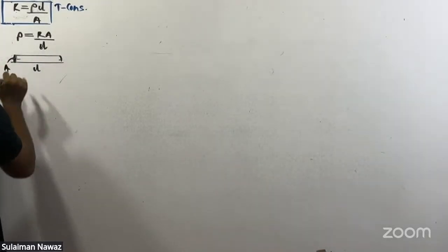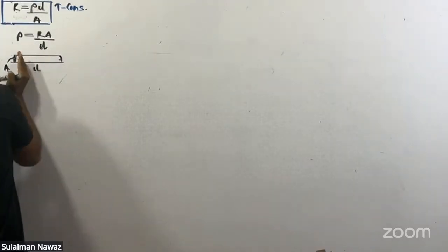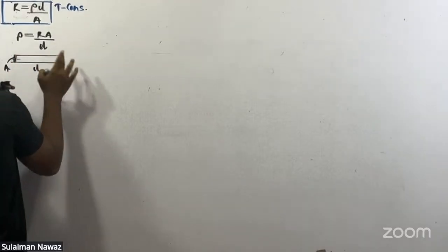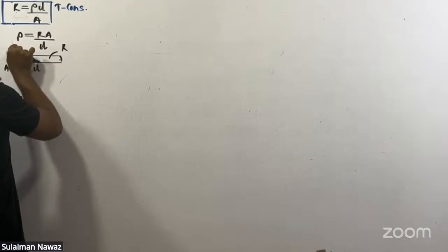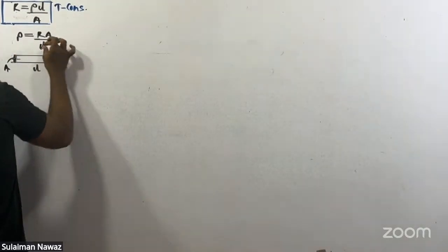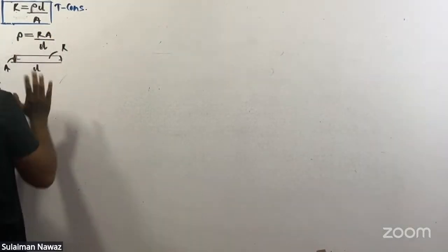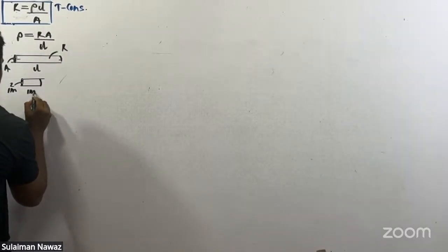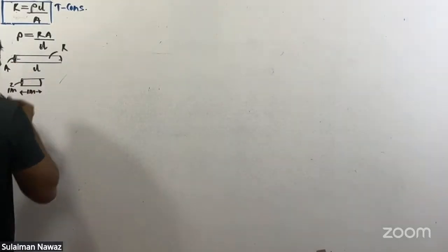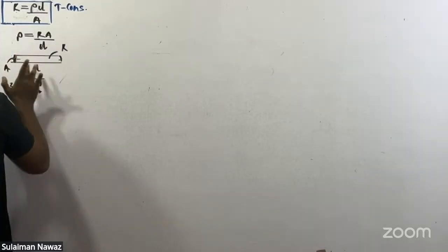and the cross-sectional area of the conductor A, the electric resistance throughout the conductor is R. The total barrier throughout the conductor is marked as R. Then what is rho? Resistivity is a property that depends on the medium, that's correct. But we can define rho as follows: consider a unit length of 1 meter and a unit cross-sectional area of 1 meter squared of the same material. The resistance of that conductor of 1 meter length and 1 meter squared area is what we call resistivity. For a conductor of length L and cross-sectional area A, the total barrier, the total resistance, is R.